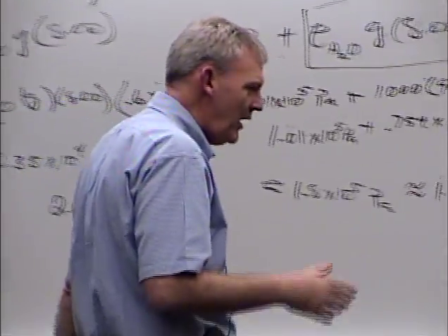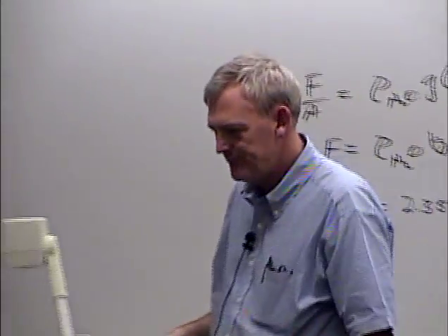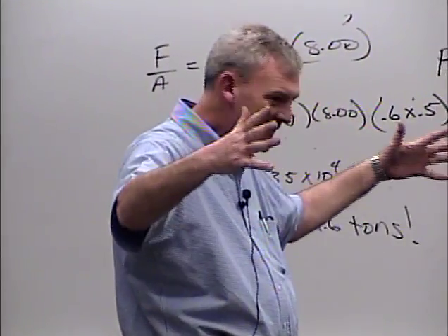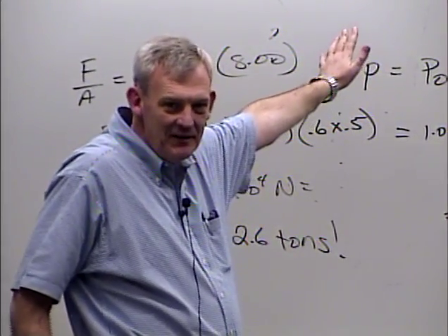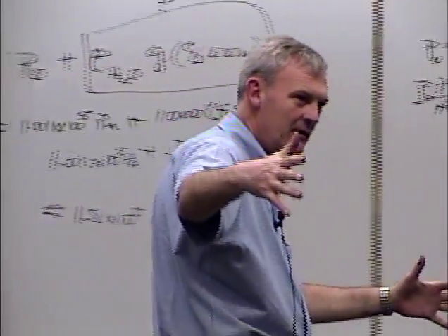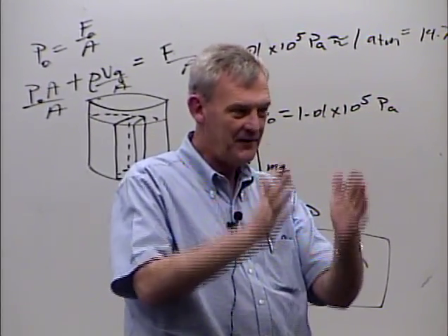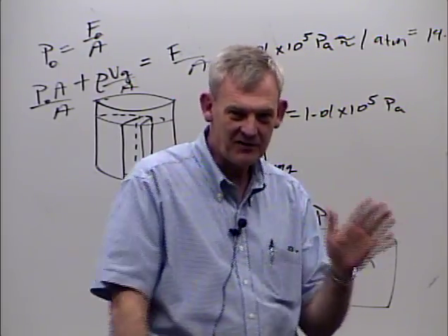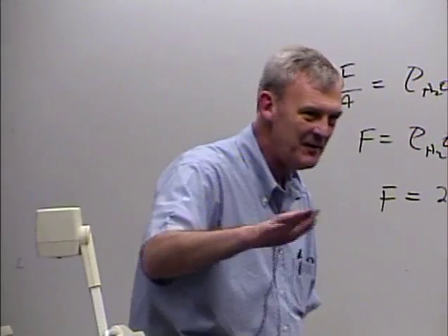So a strange thing to get used to is that Hoover Dam, which is huge and really thick at the bottom, and Lake Mead, which goes on for like 27 miles back behind it, you'd still need that big, thick bottom even if Lake Mead was only this wide, but still as deep as it is there at Hoover Dam, because the pressure would be the same. The lateral stuff doesn't do anything to the pressure.